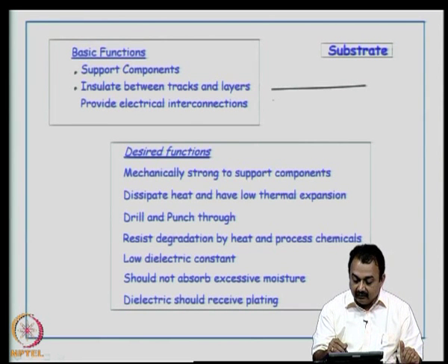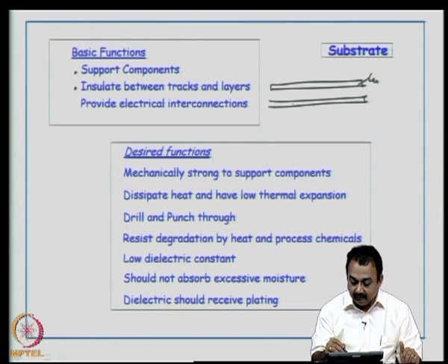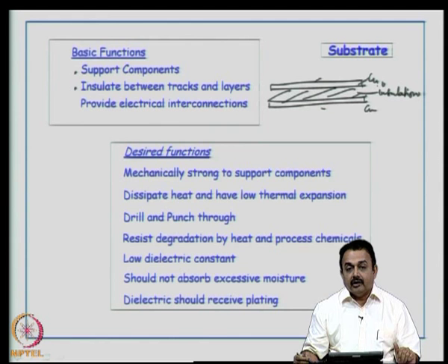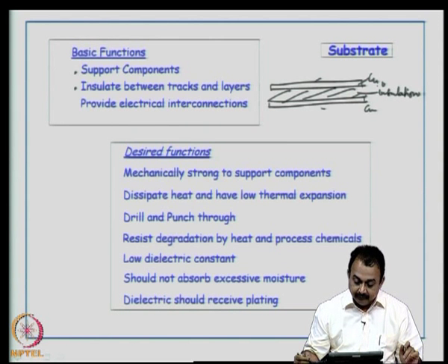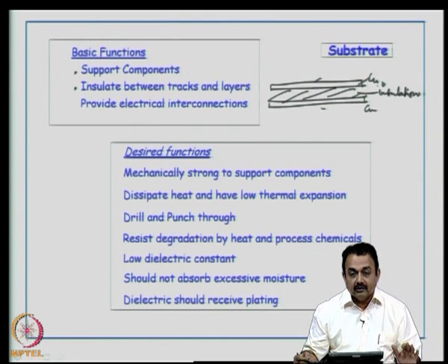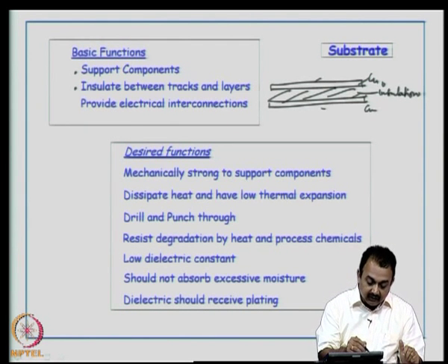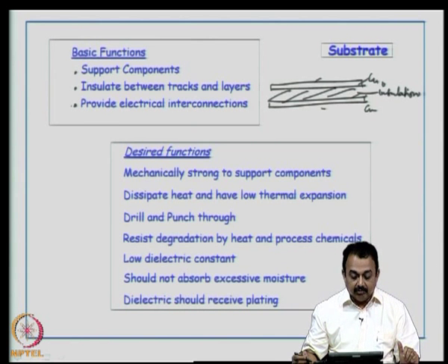Imagine a dielectric material and then you have copper here and then you have the copper here at the bottom. So, if you run tracks on top and bottom, this provides the insulation, and it also enables a very good electrical performance for your system by minimizing crosstalk and other electrical parasitics. It provides electrical interconnections by routing the copper.